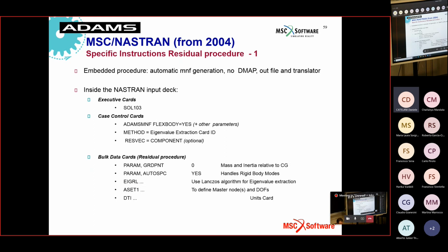So it is evident that for a typical finite element user, nothing changed. This analysis is a standard modal analysis. Lanczos method is a typical method for evaluating modes. Assigning some nodes requires the use of a card like this, which is standard. The only new thing is to remember this card: I want to have the output in the MNF format.